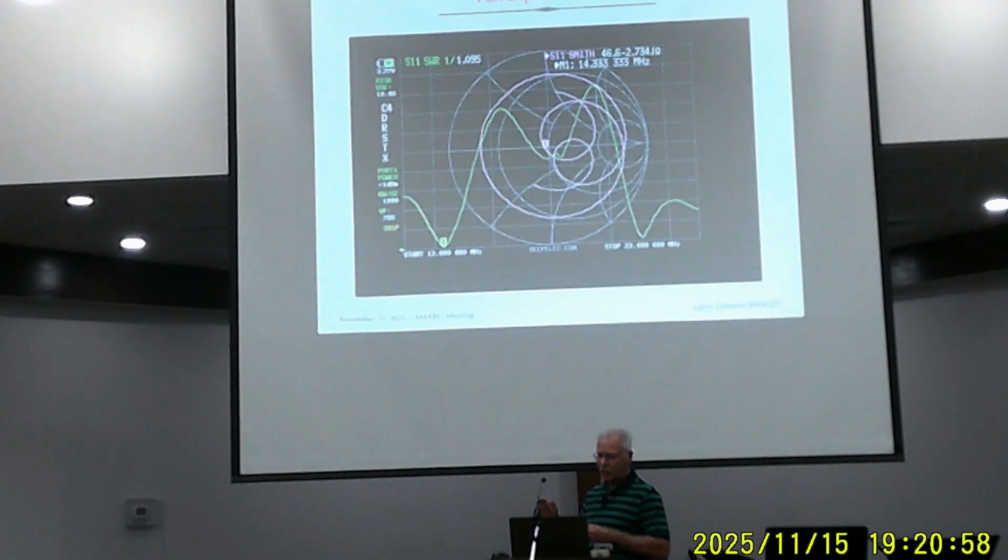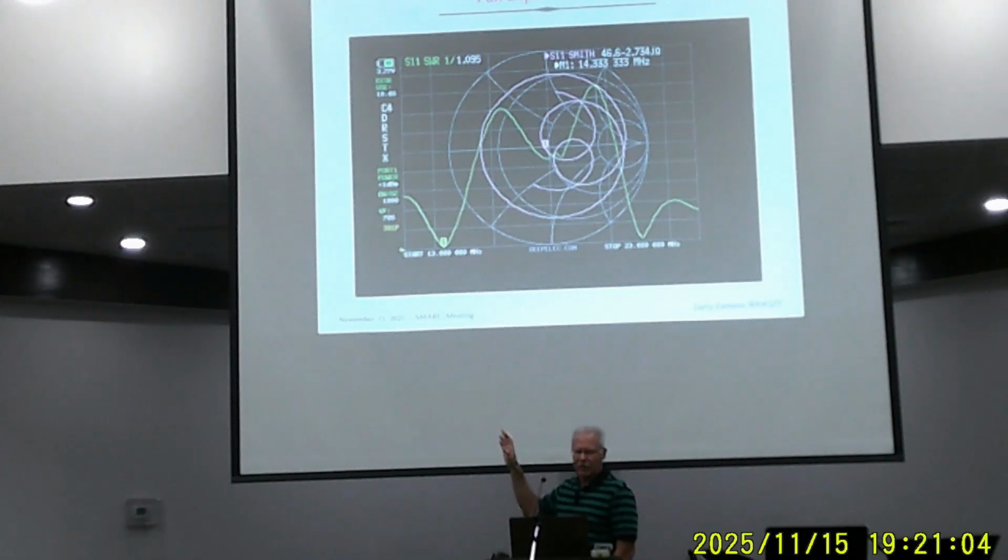So here's where they roll their eyes. Okay, so that's an SWR plot, and of course the purplish pink is a Smith chart. So again, this is exactly the same data. That Smith chart is showing you exactly what that SWR chart is showing. It's actually giving you even more data because the Smith chart tells you what the resistance and the reactance is